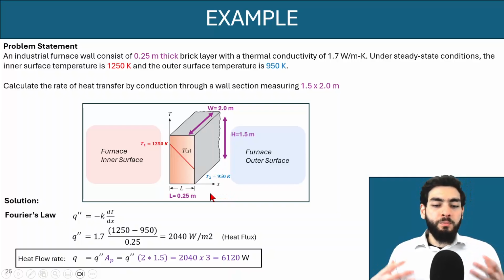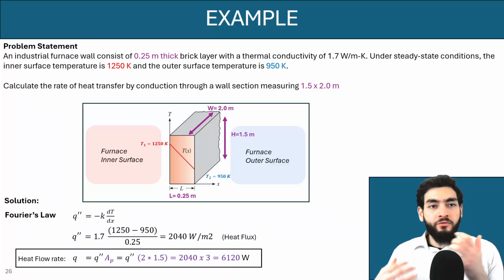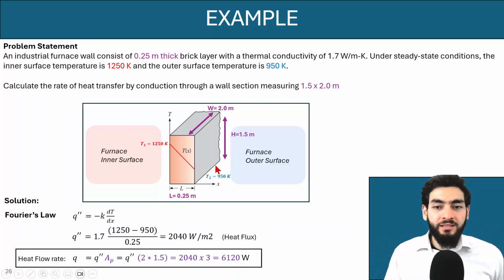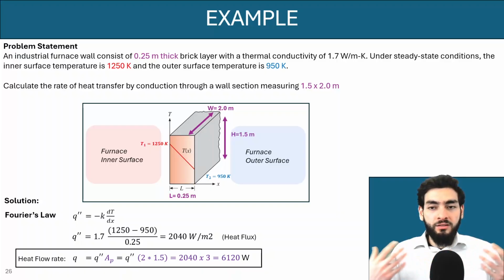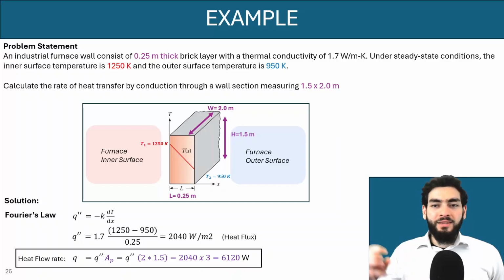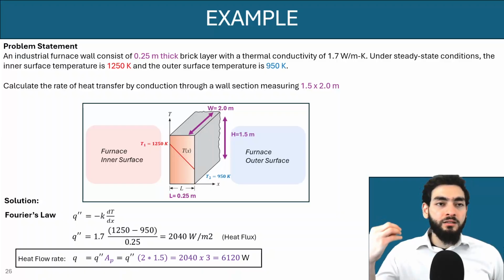It really depends on what you're trying to do. Sometimes when you calculate heat flow, you might want to err on the side of caution, and that sometimes means you want to use the more exaggerated number. However, in this particular case, a representative thermal conductivity number would be an average of both. That's something you'd see applied in a lot of heat transfer problems. This doesn't mean that the thermal conductivity is constant, it just means that whoever decided to use the thermal conductivity number assumed a representative average value.